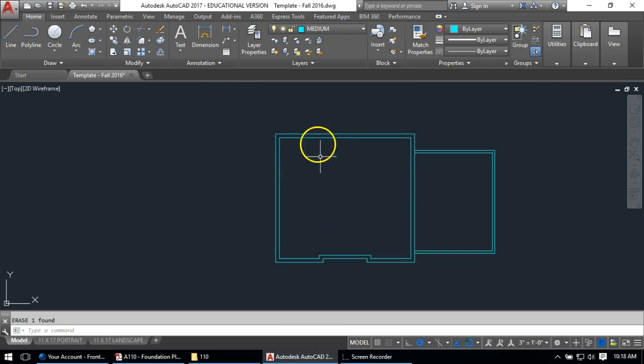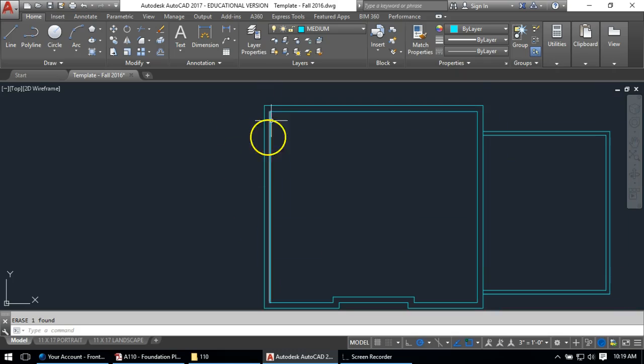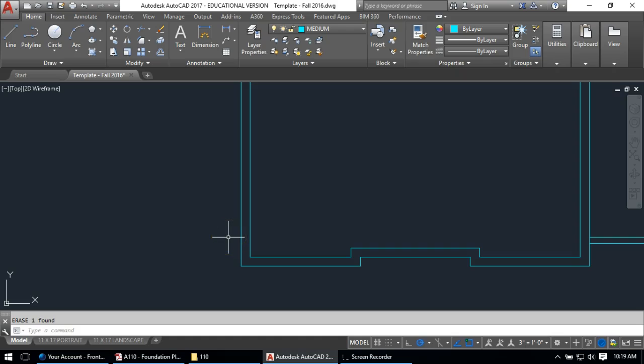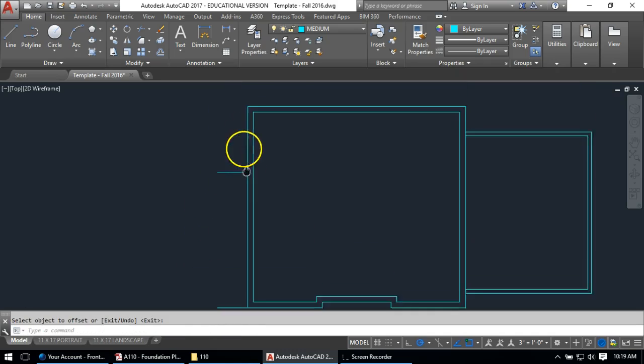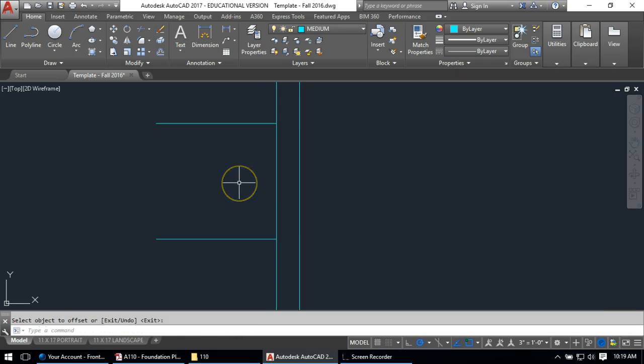But there's also another space for a chimney up here on this side. So let me come up here and say 2 foot, comes 2 foot out. And it's actually dimensioned from, even though it's closer to the top, it's dimensioned from the bottom line. And it's dimensioned up 23.6. So I'm going to draw a line out, offset that 23 foot 6 inches, it comes up here, and the whole chimney is 5 feet deep. So go up 5 feet, and it comes out 2 feet. So I'll offset 2 feet from this wall and fillet this together.